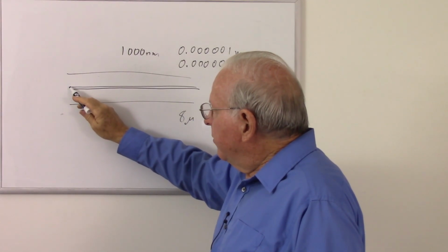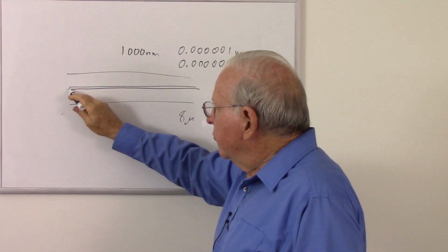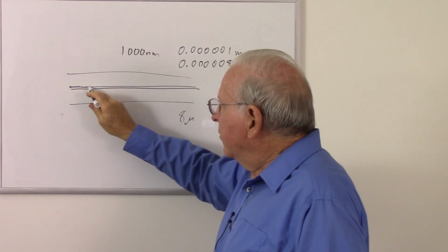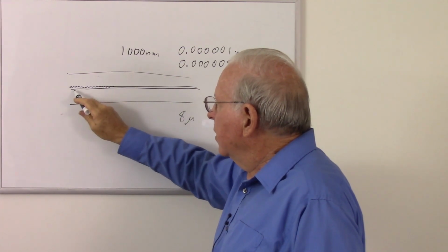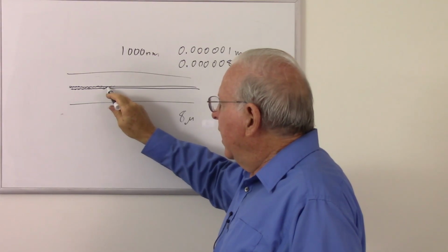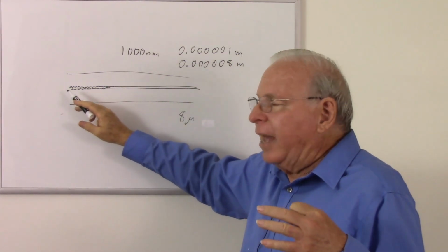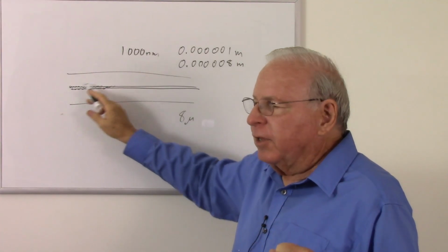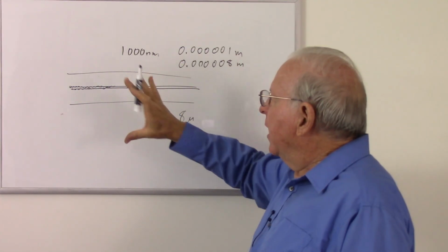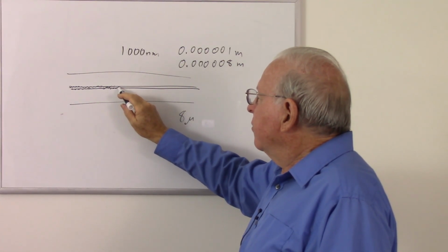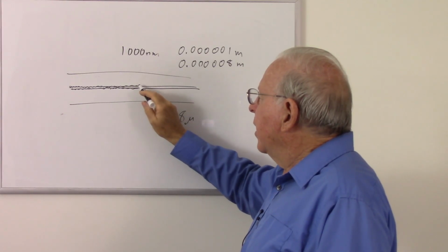Now, what happens is that the energy begins to travel down the fiber as an interaction between the core cladding interface. And we do not have any more of these reflection modes or these paths down the fiber. We have simply one. This is called waveguide mode propagation. And so there's only one mode, or one possible path.